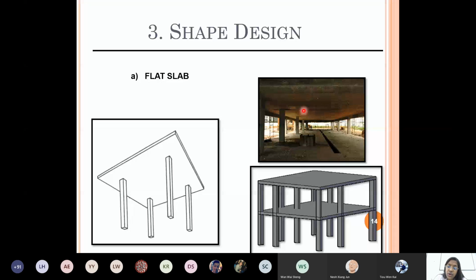Or they design it as a one-way slab, and the corresponding loading may be due to one direction. What is a one-way condition? The slab length should be more than the breadth, then you can go for one way. The load that is coming in is in one direction, so resisting the load needs to be done in one direction only. That's why the beam is not there. I mean, cross beams are not there, but the edge beam is there. Okay. Did I answer your question?